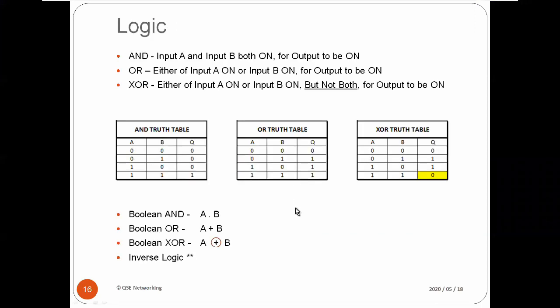Okay, cool. Right, now I wanted to just, I don't know if you've ever done this before, but everything in this PLC, a programmable logic controller, works in Boolean. So whenever you say input A and input B must both be on, you're doing an AND function.